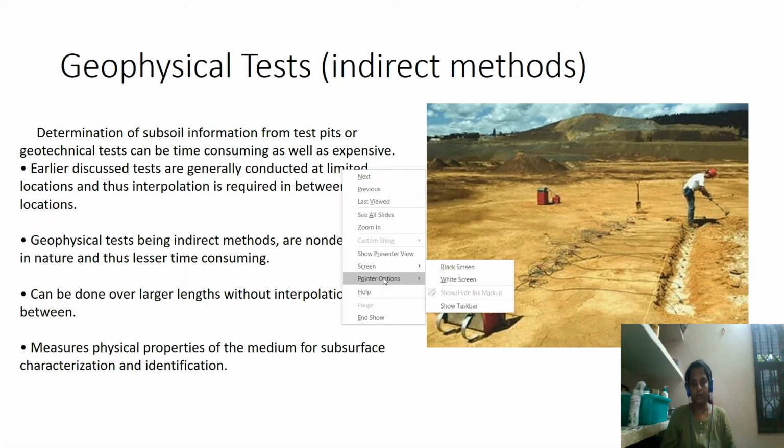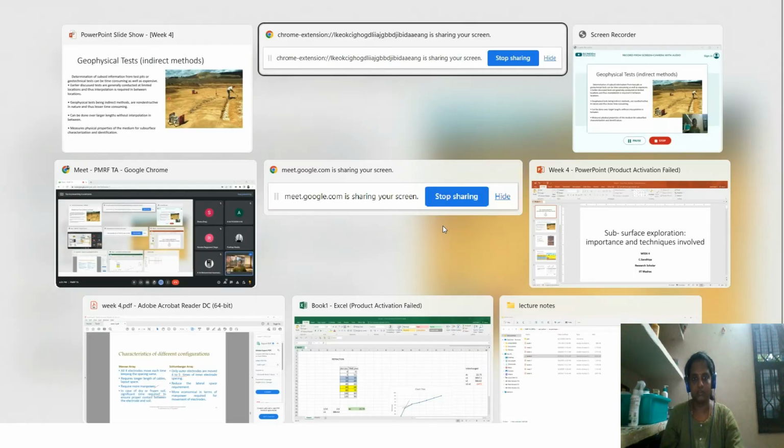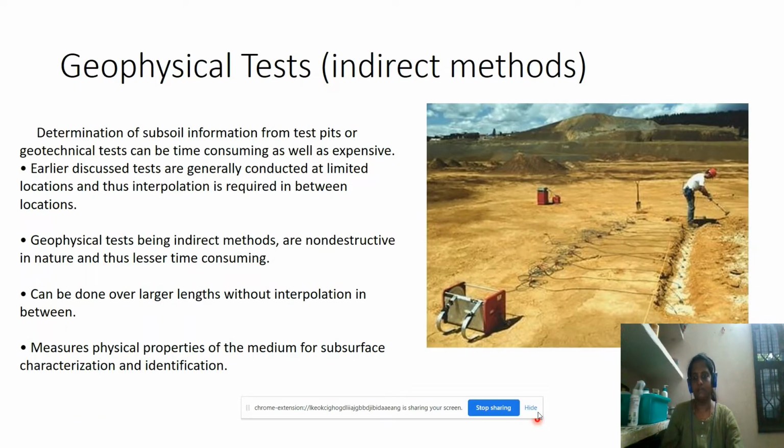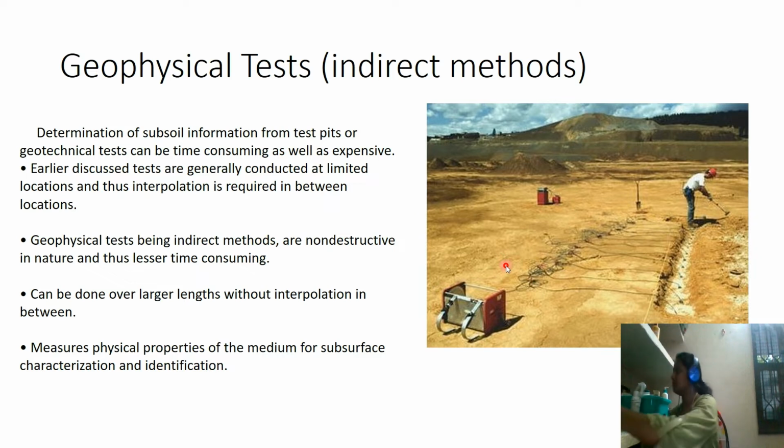If we are not able to progress our borehole after a certain depth because of a hard stratum or a rocky stratum, instead we can perform a geophysical test in order to confirm that stratum. Sometimes a boulder may also get stuck at the bottom.